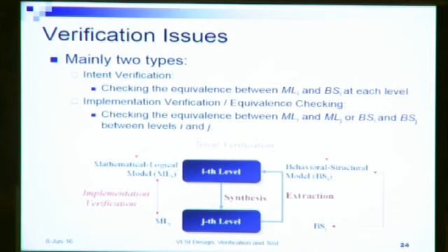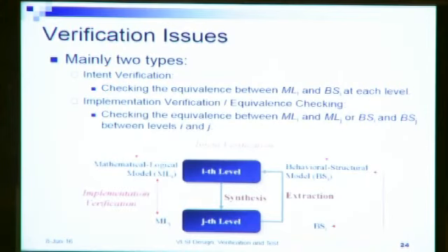We also said that this was the design flow in a nutshell. At each step of the design, right from the initial specification to the implementation, pre-silicon, we had verification to be done. So we need to verify that the design is correct at each stage of the design, right? When we are doing a synthesis from a less detailed one to a more detailed one, errors can come up, and we need to verify that there are no errors with respect to the specifications that I have.